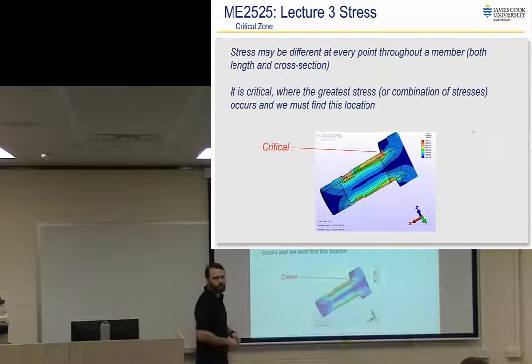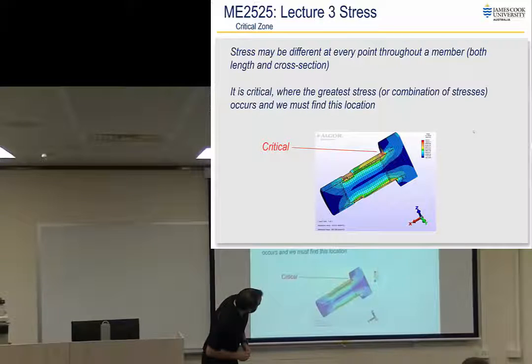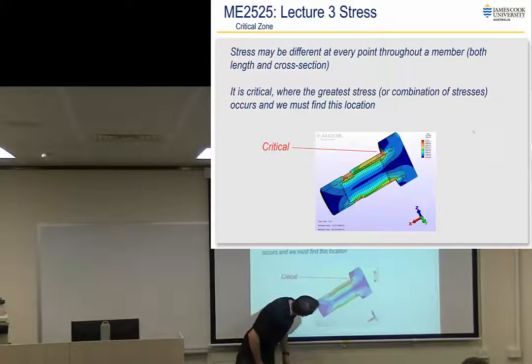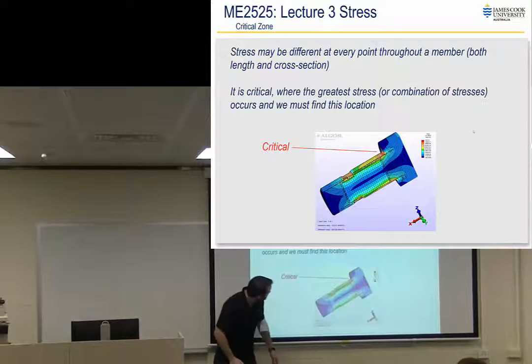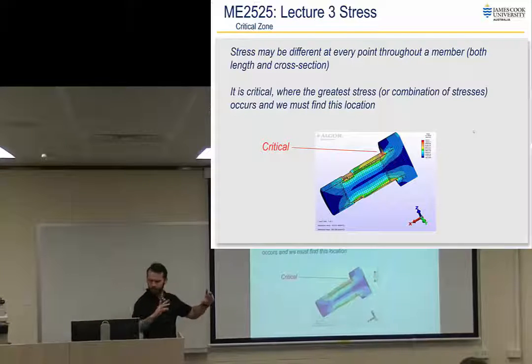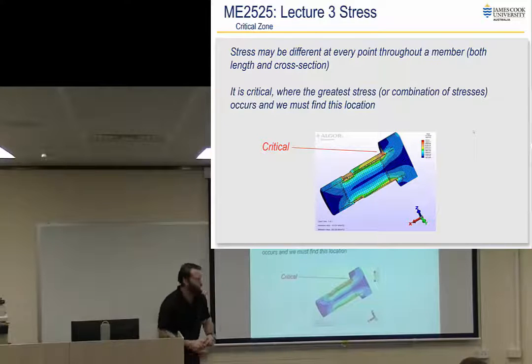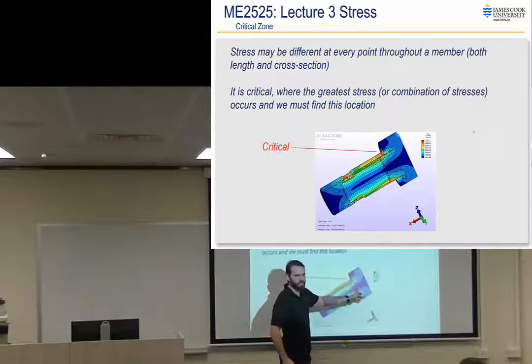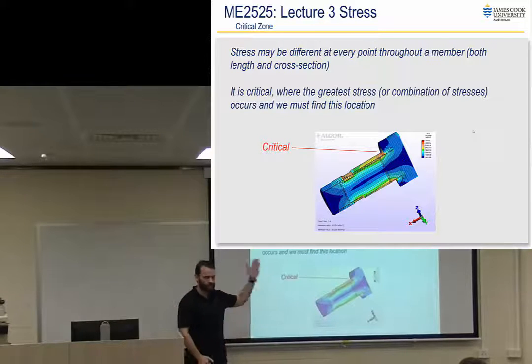All right. Sorry, Dave, is that a bolt? I think that's part of a larger roller. So that's the shaft of a large roller, I think. That's a section there. Yeah, this came from a previous lecture slide where that roller was, I think it's about that diameter from memory. And that roller was actually fatiguing at exactly that point and causing slow fatigue cracks coming down like that. That's a cross section, yeah. That's half, and it's half this way as well.